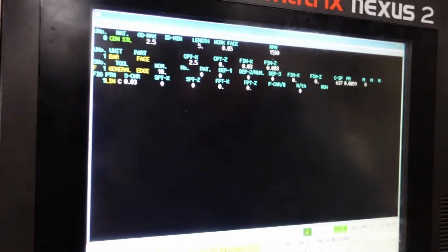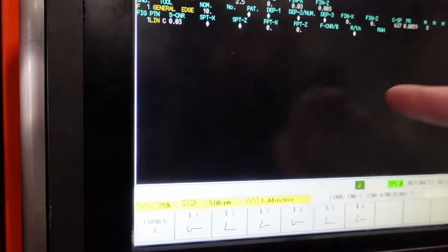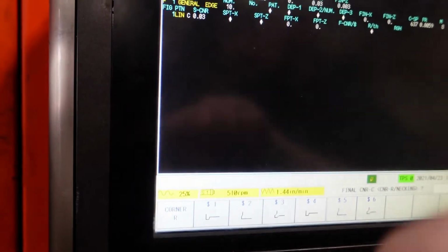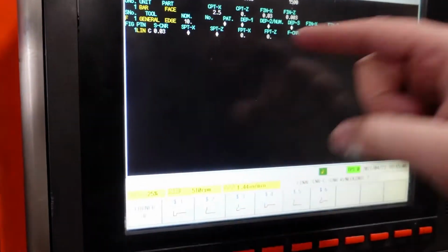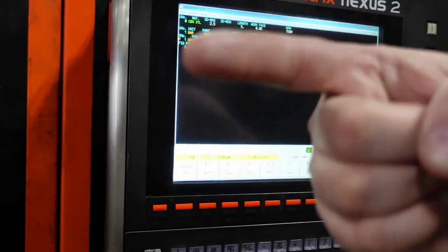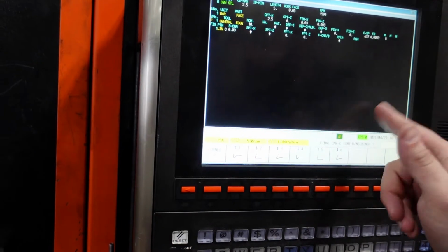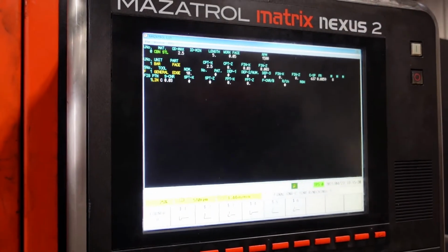If I want to do a final corner, which you can't necessarily do on a face, it doesn't make sense. Why would I do a corner here or here in a face? I had to think about that. I would write a separate program to come in with an undercutting tool of any variety that's faced in Z to come and cut a corner or a radius in the face of the part. So you don't have to do anything.